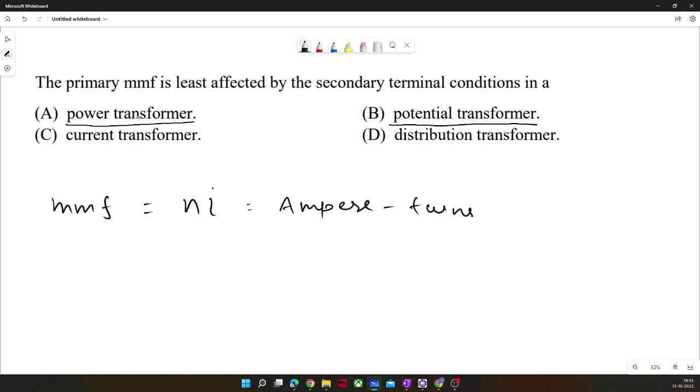Transmission lines, where after generation the power is needed to transfer. Generally, we do not prefer to transfer low voltage, high current through a wire due to the obvious reason, the losses. So we always try to transfer high voltage, low current.